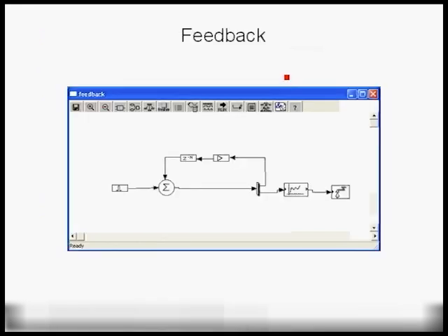Okay, so the next important topic is of course feedback. In any block diagram communication system, we need to figure out, for that particular simulation model or simulation kernel or methodology, how does it handle feedback? Here we show a simple feedback system in which we have a low-pass filter implemented discretely. We have an impulse that generates an impulse, in this case a 1 followed by 127 zeros, for example, for 128 samples. You can actually specify to generate more samples.